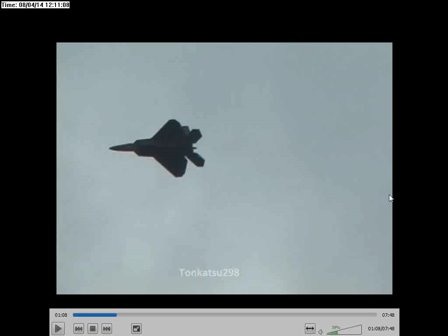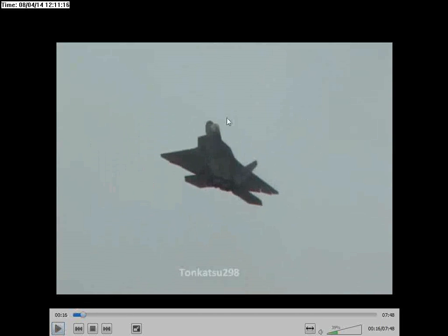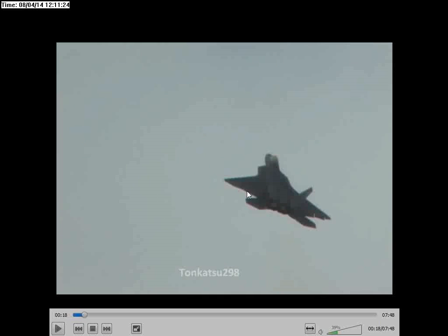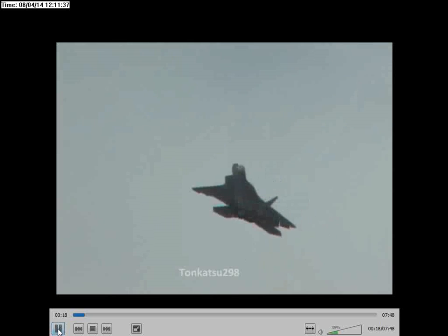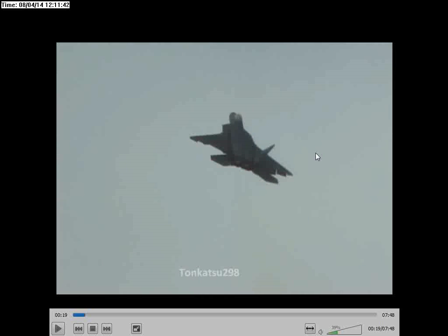But also the controllability becomes an issue as well, because while the aircraft stands still in the air, in this case none of the aerodynamic surfaces work, right? Because the aircraft is not moving, so there is no airflow around the wings. So the pilot cannot use the elevator, he cannot use the ailerons or any other things. So he has no control whatsoever. So to be able to control the aircraft in such a case, you need to have some way of changing the moments, and this aircraft uses thrust vectoring.